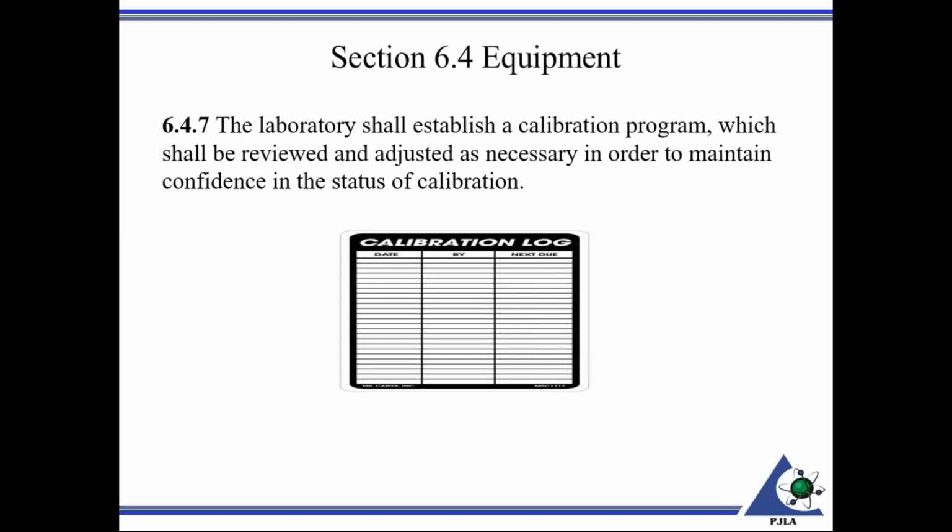You can also look at risk. So one thing under non-conforming calibration or testing, when you send instruments for calibration and they're out of tolerance, then you might have to implement non-conforming calibration and testing work. So, for example, if you just blanketly put a 5-year interval on the program, you could possibly have to go back and do an impact analysis covering 5 years.